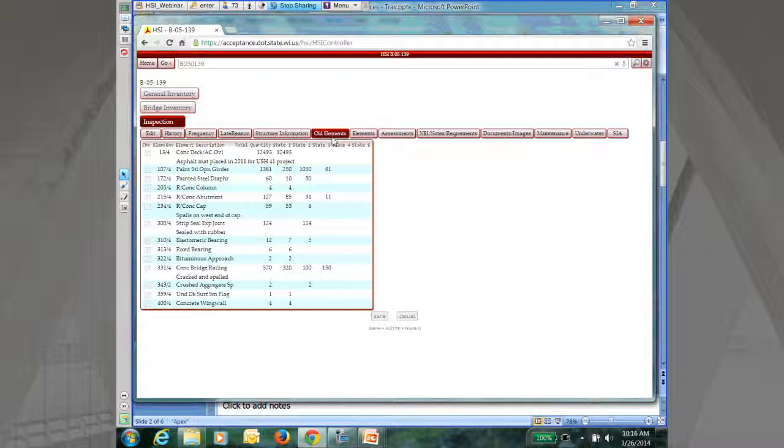That's important, particularly for your first round of AASHTO inspections, because what we had to do, that Rick actually talked about earlier, was a pretty intense data migration process to get to the new AASHTO elements, which are on the other tab. That process isn't 100% accurate in some instances. You're looking at language with 5 condition states for, say, a deck that are going to 4 condition states.